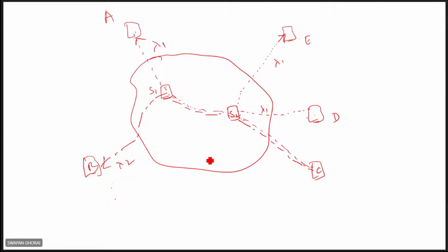So to avoid this, we need wavelength conversion. Wavelength conversion means information from one wavelength is converted to the other wavelength. And in fact, the wavelength itself is not converted. Information carried in one wavelength is transferred to another wavelength. That is called wavelength conversion. So though the term wavelength conversion is used, actually information is transferred from one wavelength to the other. I'll give you simple examples.